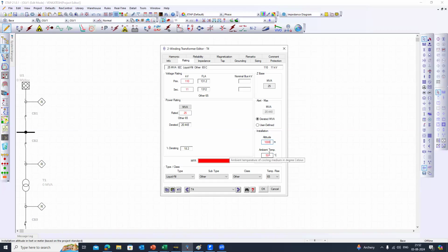Now, as you are telling, if you put the transformer in the AC control room, and if you are able to maintain the transformer for the ambient temperature of 30-degree, of course, the ambient temperature, what I am referring to is the room temperature also. With the air conditioning system, if you are able to maintain the temperature of 30-degree, then definitely you can go for 25 MVA. If you are able to maintain the temperature of 20-degree, yes, you can use the transformer up to 20.27 MVA also.